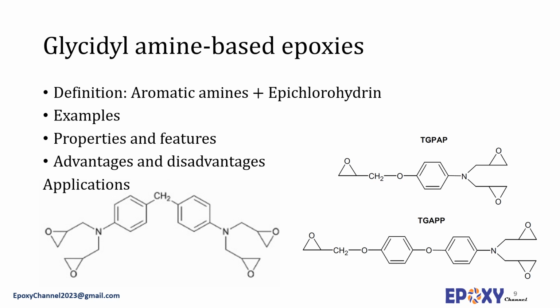transmittance, and weather resistance. And for application, glycidyl amine epoxy resin is a common resin matrix for high-performance composite, which is characterized by multifunction, low viscosity, high activity, etc. It is also suitable for glass fiber, carbon fiber composite materials for aerospace, such as airplanes and rockets, heat-resistant solvent-free coatings, electrical insulation materials like electrical insulating epoxy, heat-resistant adhesives, and other high-performance applications.